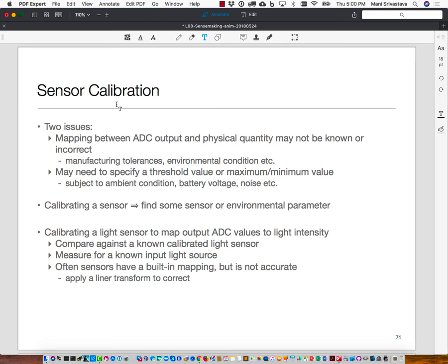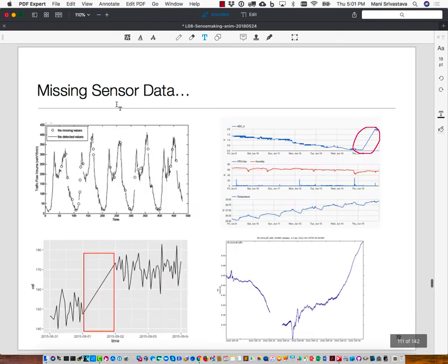In some other cases, like chemical sensors, the relationship can be much more complicated, and you would have to rely on understanding what the calibration curve looks like. So for example, temperature and frequency of a quartz crystal are related in a cubic manner. We know that's how the underlying mechanics work. So knowing the physics of the sensor can help you calibrate. So conditioning, calibration, and dealing with the noise.